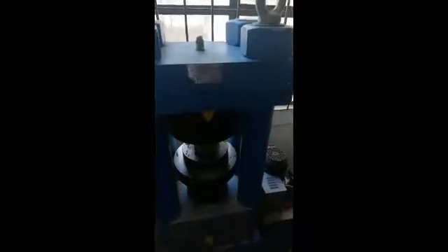After the cubes were taken out of the curing bath, they were measured to check whether the dimensions were still compatible, or still the same shape. All the dimensions of the cubes were 10 mm. The compressive strength was then measured in the lab. The compressive strength was measured for all the cubes, from the first cube to the third cube.